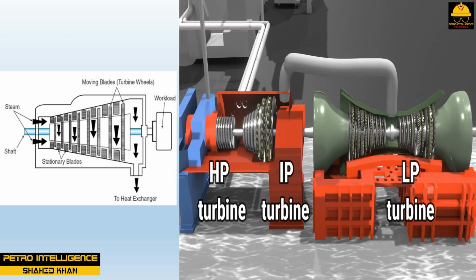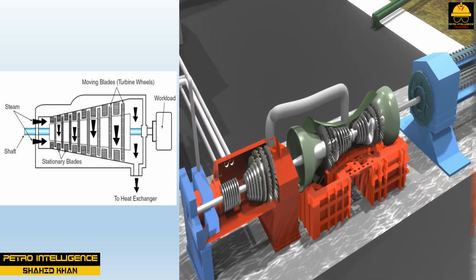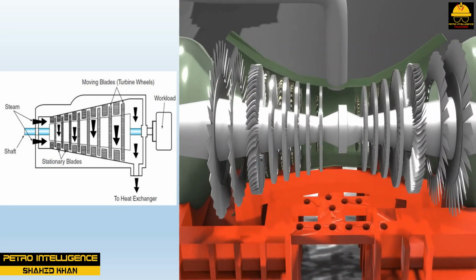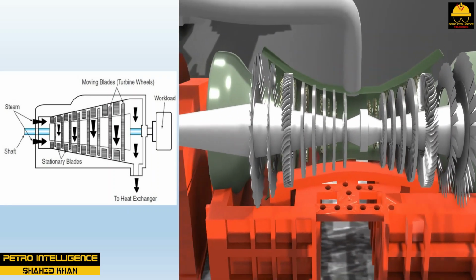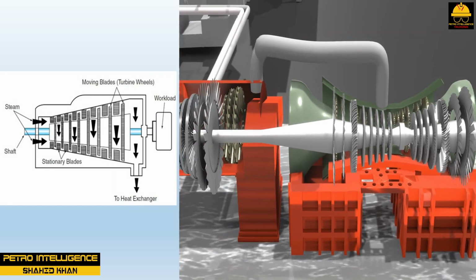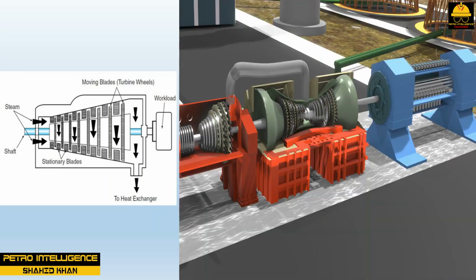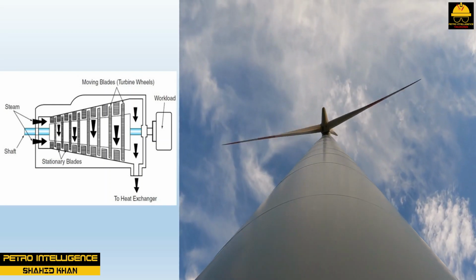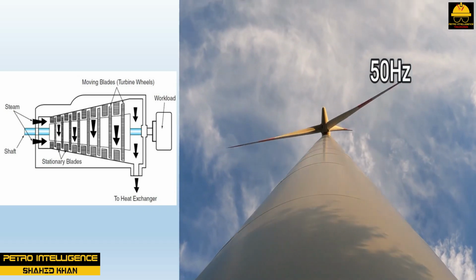Impulse turbines have a blading design that causes rotation of the blade and shaft assembly, or rotor, when high-velocity steam pushes on the blades. The kinetic steam source is external. Reactive movement occurs when steam escapes from a fixed nozzle attached to the rotor, propelling the rotor. The kinetic steam source is internal.